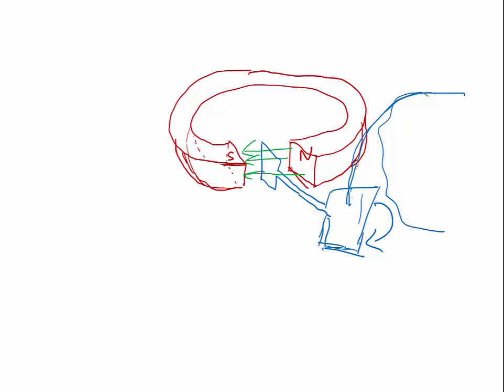So every generator that we have, whether it's a thermal generator which uses coal, in that case you end up boiling water and have steam go up a shaft at a high pressure to turn the turbine. If you have a waterfall, you can see how that'll turn it. And if you have a nuclear power plant, generally that also creates steam at a high pressure by using nuclear energy, which then spins this turbine.